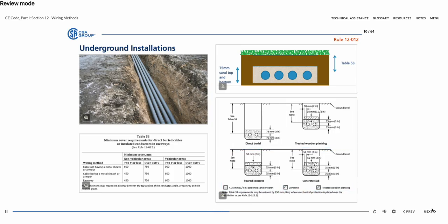Please note, if the conductors are 1/0 AWG or larger, use IEEE 835 and Rule 4-004, Sub-Rule 1 and 2 to determine ampacity ratings. The underground installation requirements are found in the IEEE Standard or Appendix D, Tables D8 to D11.